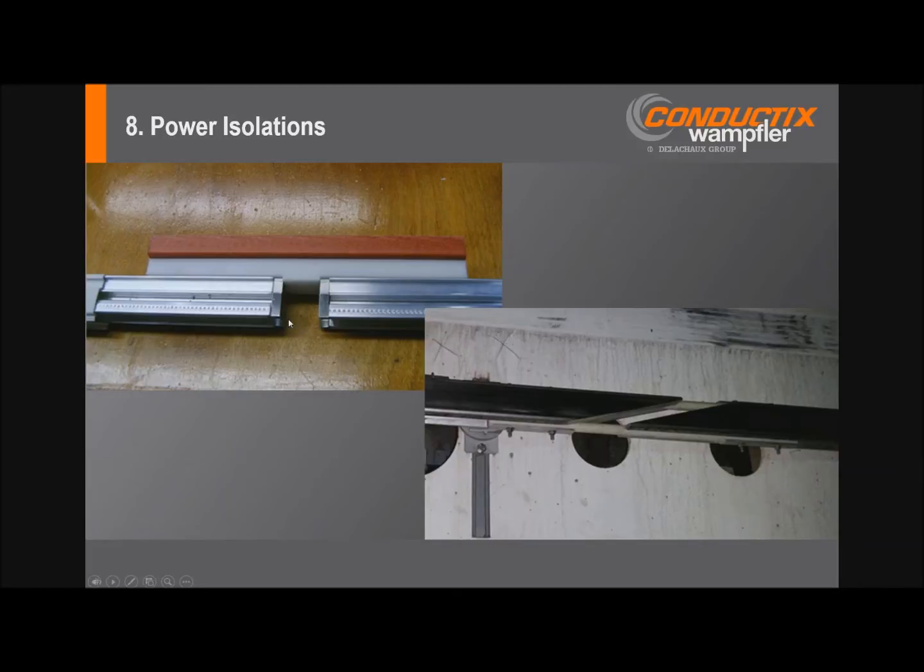You'll notice this open air gap provides better tracking and isolation, because over time these will accumulate dirt, debris, moisture, and collector dust, and become conductive. So there is a bit of maintenance to these, or there can be.